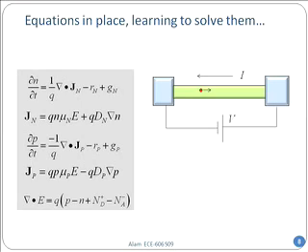We know drift and diffusion equations. We know the continuity equation we just derived. Now, if you have to solve it, there would be a problem. Do you see why there might be a problem? First of all, how many unknowns do I have here, do you think? I have 3 unknowns. Do you see? Electron number, hole number, and the electric field or potential.